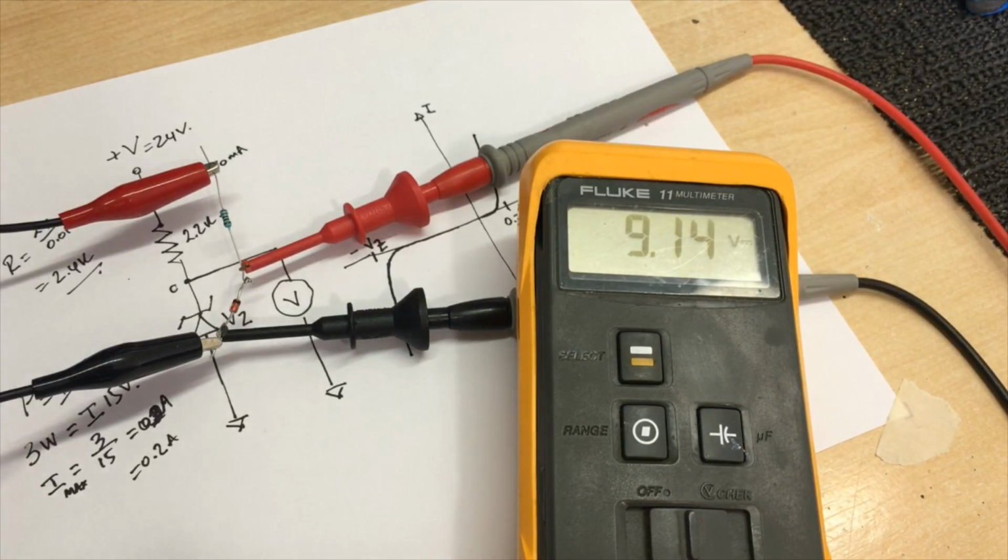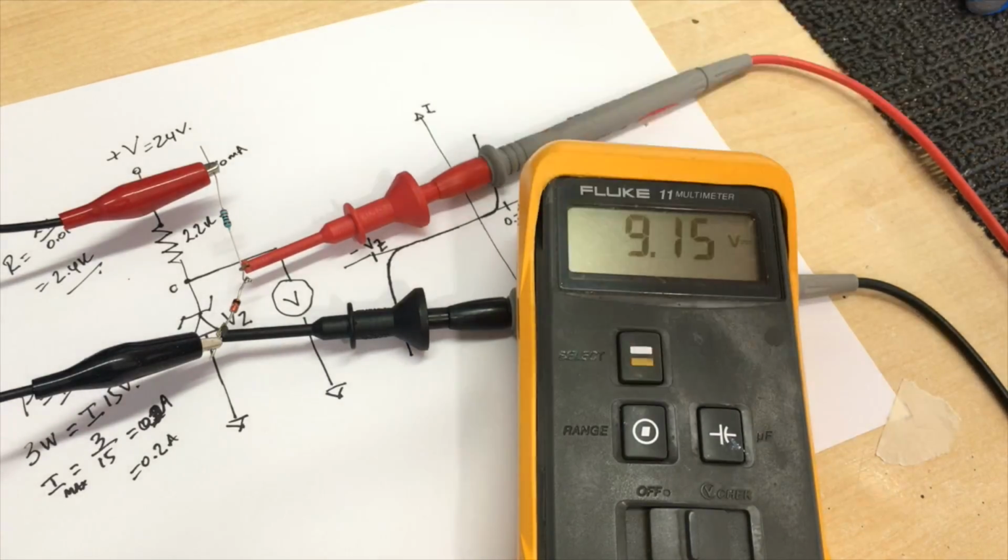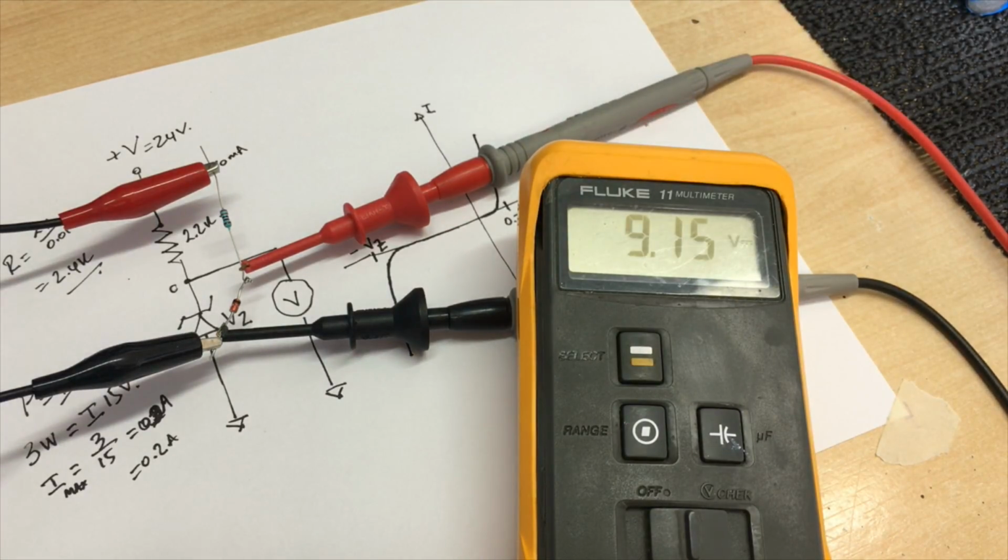You can set it up and you can find out what your Zener voltages are. But it's a pain to do this if you've got a whole number of Zeners lying around. Some of them might not even be Zener diodes. So to set this up every time you want to measure the value of a diode is just too much. There are ways we can make this simpler by building a dedicated Zener voltage tester.